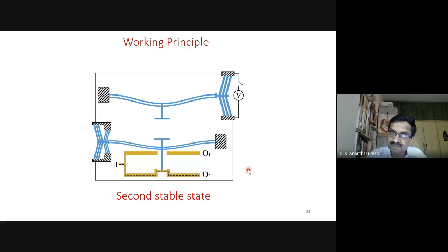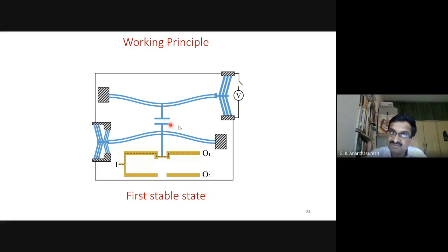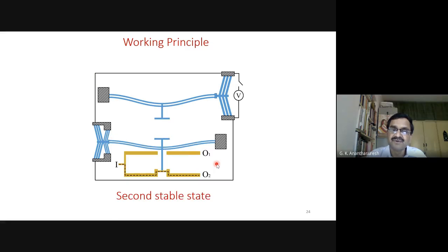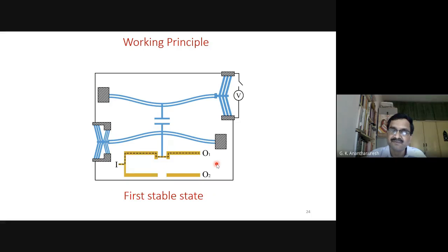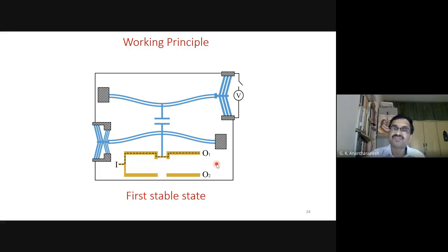Now if I want to remove it, I apply voltage. The same thing again on this one and this one. I do that. Now this starts going initially that way, retracting. So this actually comes back, and then that actually moves forward. That helps it to switch back here. It comes this way. Let me play this again. So initially it is here. We actuate that, it moves down and goes back, stays there. Now I apply voltage again, and then it comes back. So I can switch back and forth by applying the same voltage but different durations.